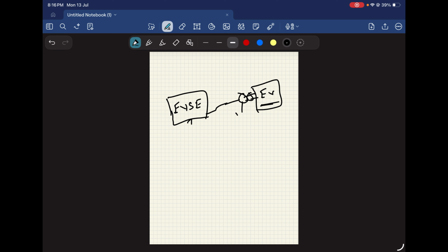In the EVSE charging station there are 3 types of supplies: one is 12 volts, one is PWM, and one more is minus 12 volts. First, initially one resistor will be there, connecting to the EVSE at this end. On this side there is one diode, here one resistor, here one resistor and one switch. This end will go to the electric vehicle.